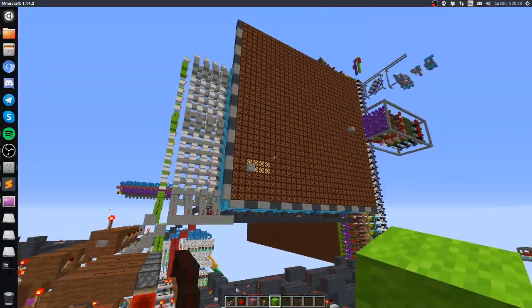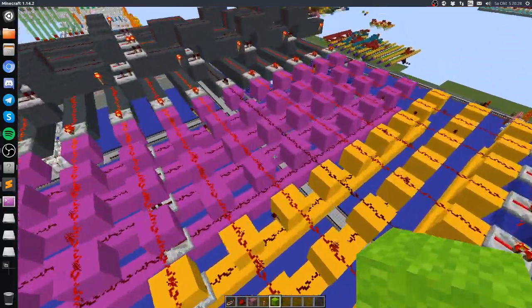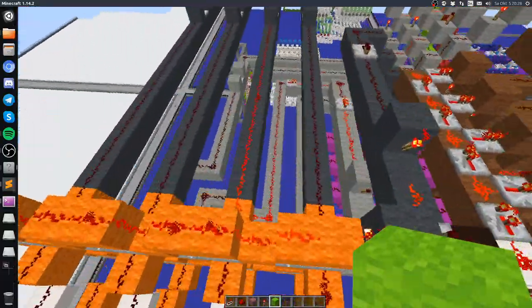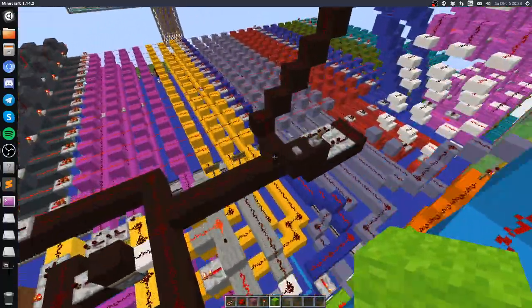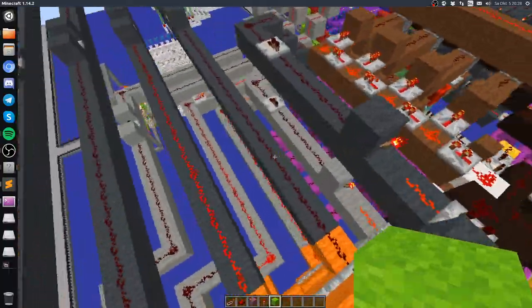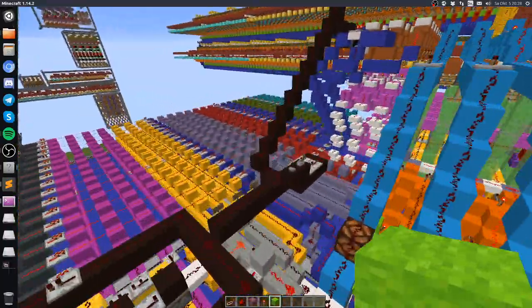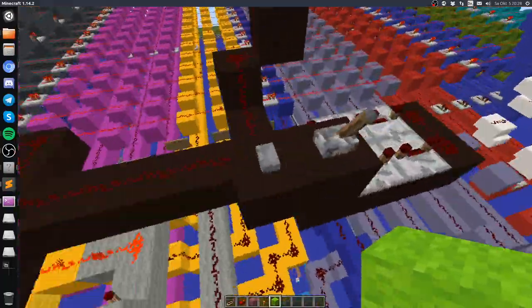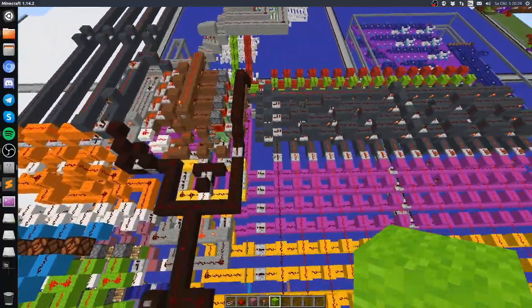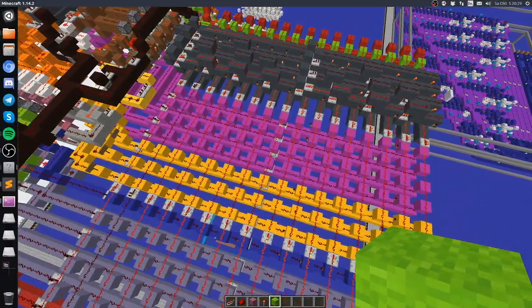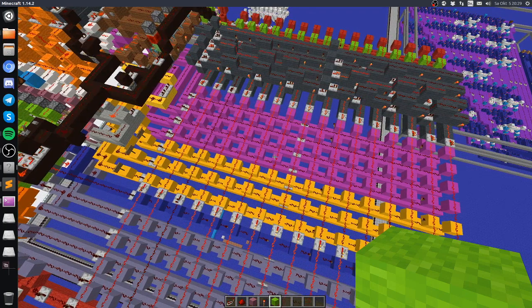Now it decided to go in here, so Y should be increased by 1. Y is 2 and not 3, so let's go in here and we're going to see that this is now 3, as it's supposed to do. What I'm going to do is reset this again and let it loop once over. But this time we're going to keep a good eye on this and see if it jumps, because if it does, that means we have a timing issue.